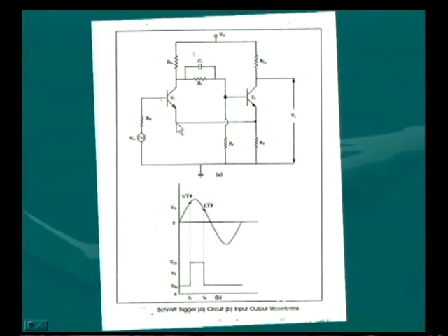So here it is 0 and this is plus VE2. If it is 0 volts and this one is plus VE2, then the base-emitter junction is reverse biased. Then T1 will be in off state. So at this time, let us apply some input signal, which is a sinusoidal wave as shown here.